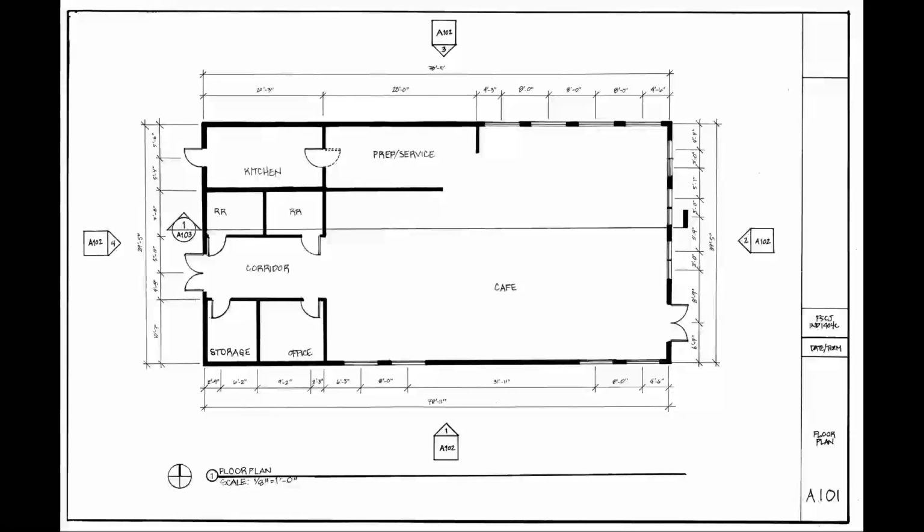In this video, I'm going to show you how to create a section and annotate a plan drawing to coordinate with the section sheet. So once again, we're looking at a floor plan here, and the floor plan, if you have not noticed already, is really what we use for all of the annotations for the drawing set so that it doesn't crowd up the design plan, which is always going to have additional content on it.